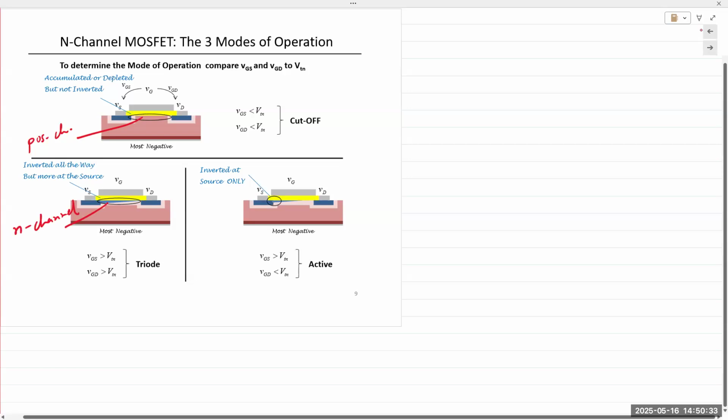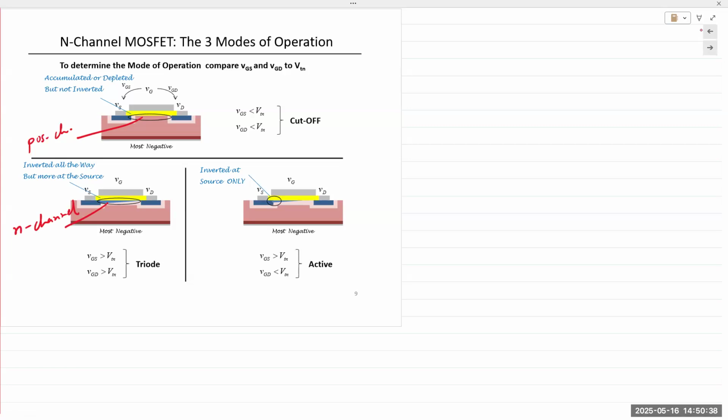The N-type drain and the N-type source have electrons. And now right at the surface of that semiconductor device, meaning right below the gate area, you have an excess of electrons. There are electrons pulled from the bulk of the substrate, as well as electrons from the drain and the source. They all intermingle. They form one continuous region between the drain and the source.